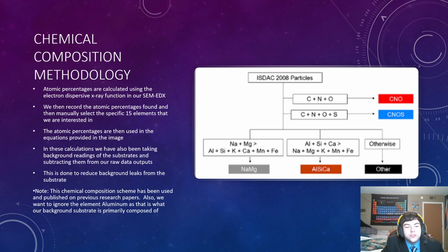We have also been taking background readings of our aluminum substrates, and I'm subtracting those from our actual particle EDX output, our atomic percentage output. The reason I'm doing that is to hopefully counter any leakage coming from the aluminum into our readings.